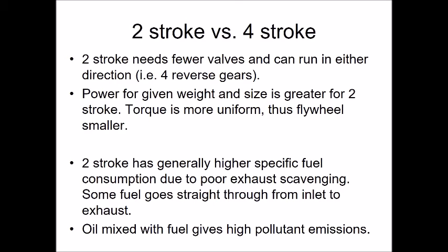What would the emissions from a 2-stroke engine look like compared to the controlled, very highly coordinated four-stroke engine where the valve doesn't open until we're sure that everything is finished? So we get really bad exhaust scavenging like that, and actually some fuel just goes straight through the combustion chamber. It doesn't get the chance to burn. It's actually burning on the way out. So imagine what kind of a noise a two-stroke engine is going to make. We'll actually see in a minute because we've got a video comparing the two together.